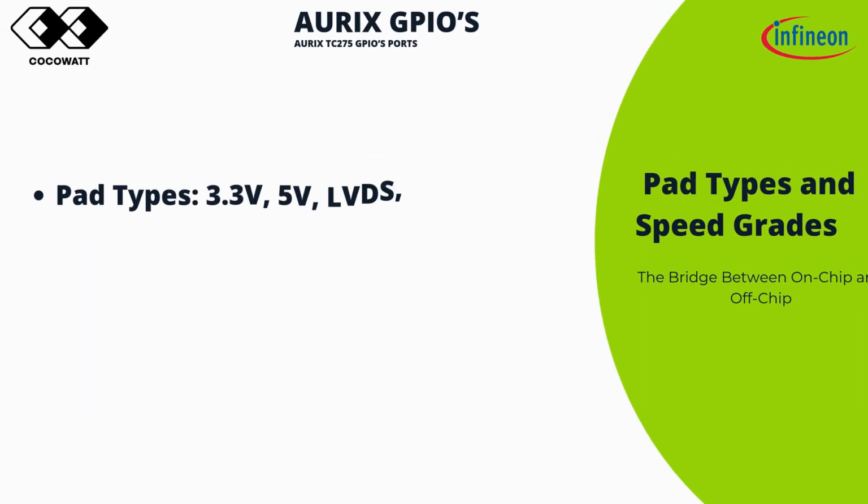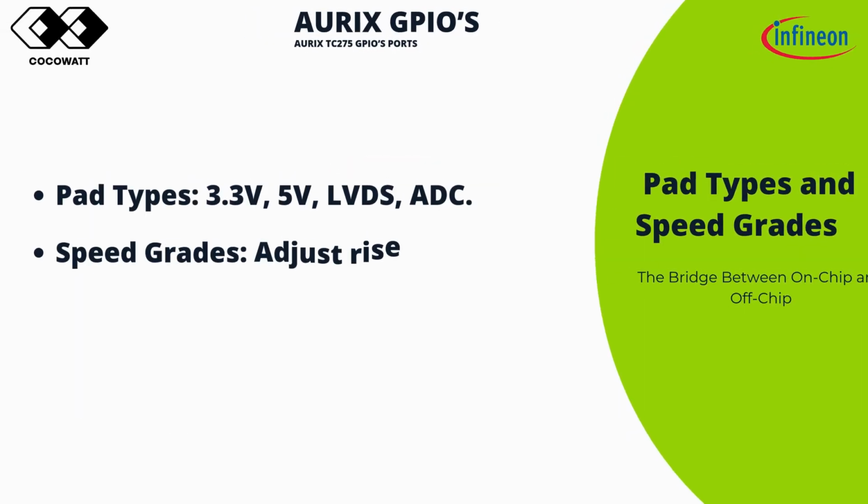Okay, now let's move on to another important concept, pad types. The TC275 supports various pad types, each optimized for different types of connections. 3.3 or 5 volt switch pads. These pads can operate at either 3.3 volt or 5 volt, making them compatible with most industrial and automotive devices.